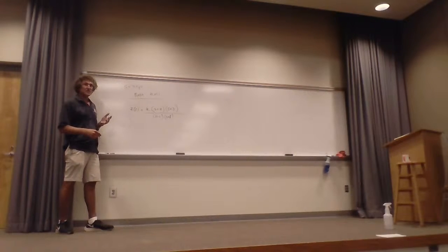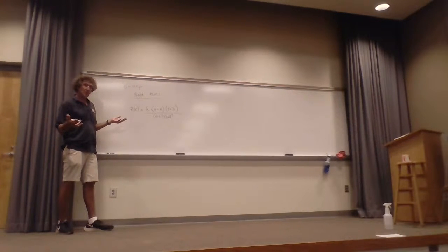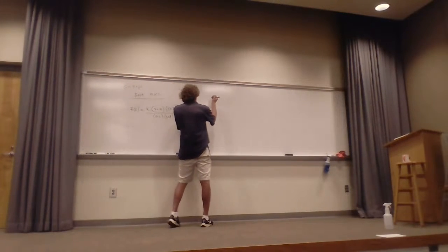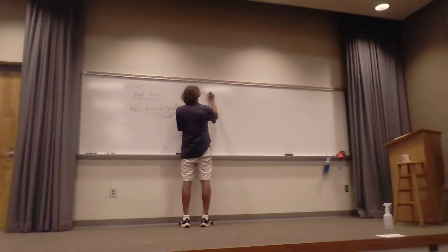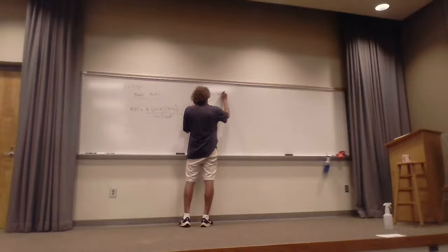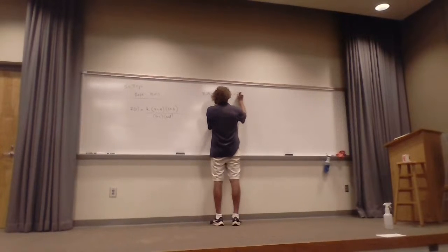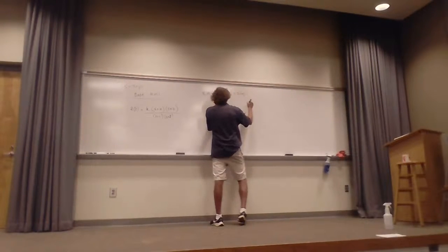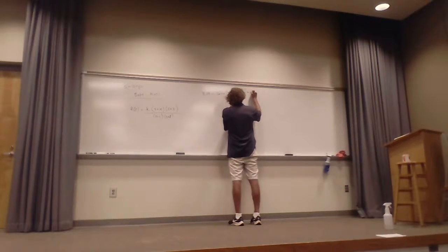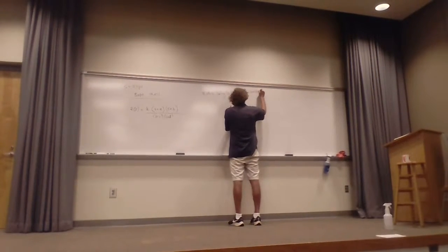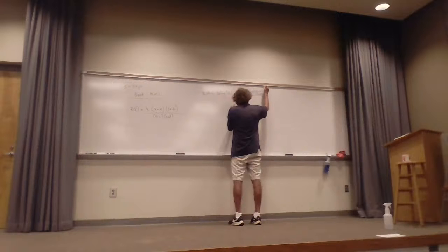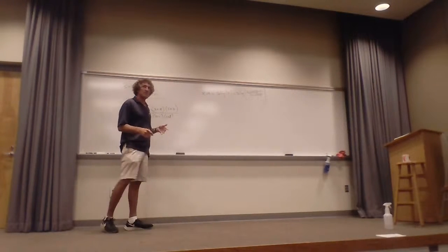Now that in itself, if it's an impedance, is in ohms. But the way we usually talk about these things, we talk about it in terms of a Bode plot, or what we'll do is take 20, we'll call this Z in dB, we'll take 20 times the log of the magnitude of Z. And in our case, that's 20 times the log of the magnitude of K, S plus A, S plus B, over S plus C, S plus D. I'm just showing you the way it's usually done.